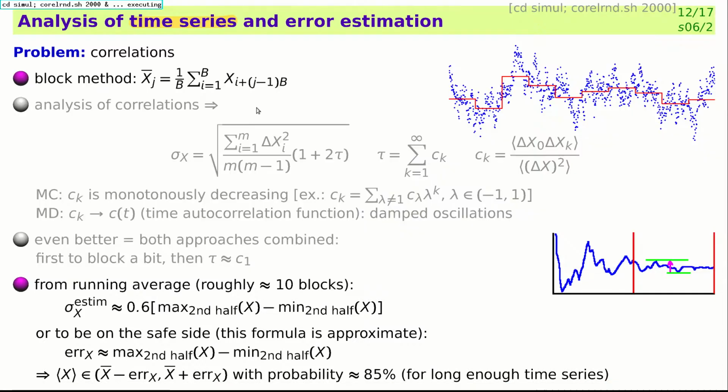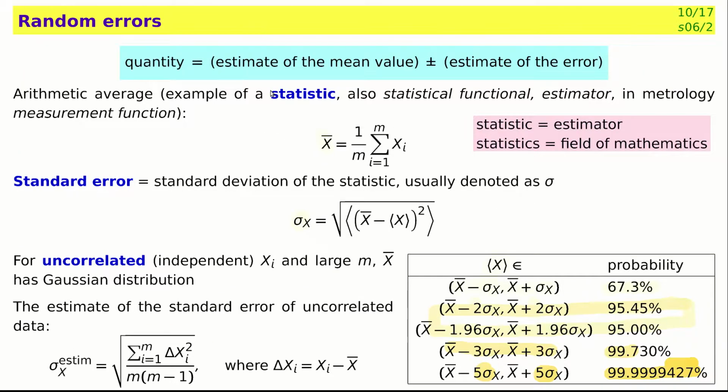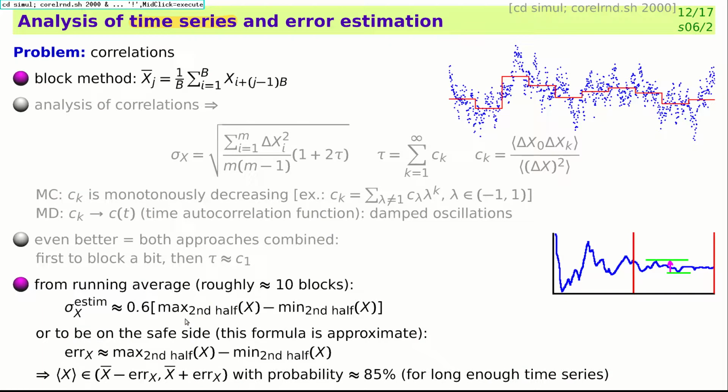And it's difficult to handle this by statistical methods. So, in turn, we cannot use this simple formula in simulations. At least we cannot use this simple formula directly. But we can use the so-called block method. We have such correlated data like here, and we split our convergence profile or trajectory of measured data in time into blocks like this.